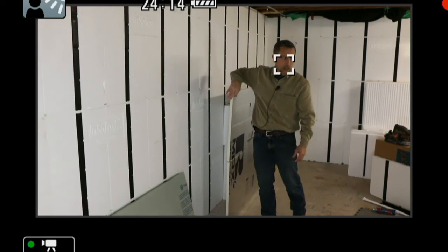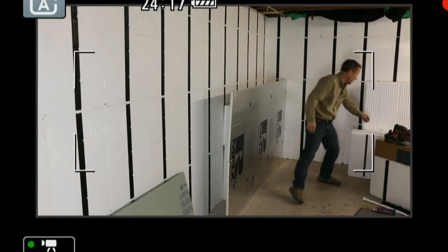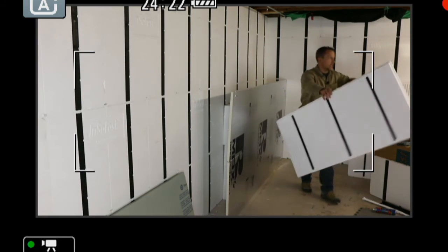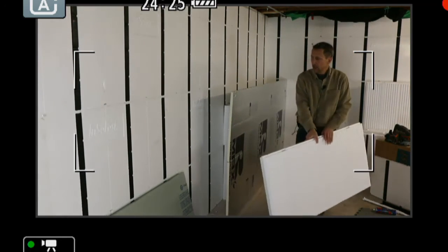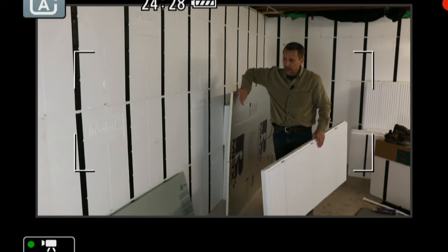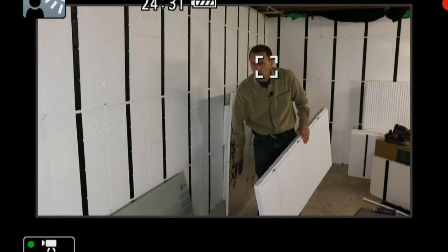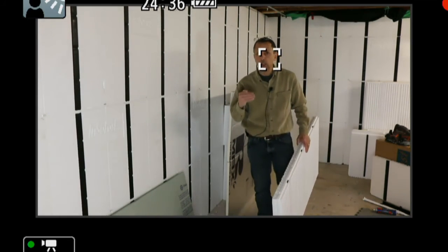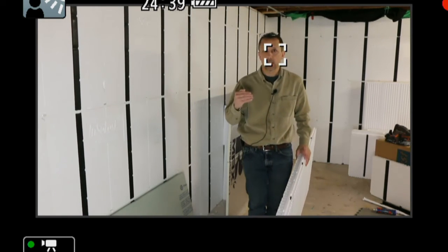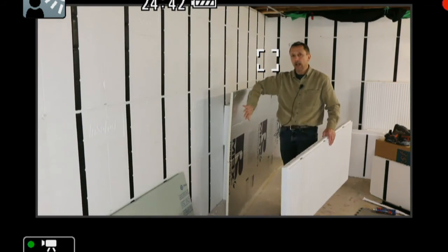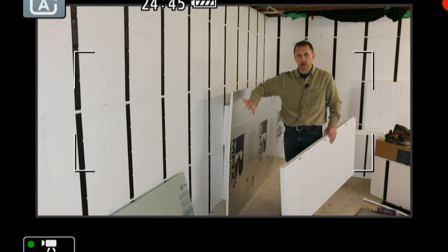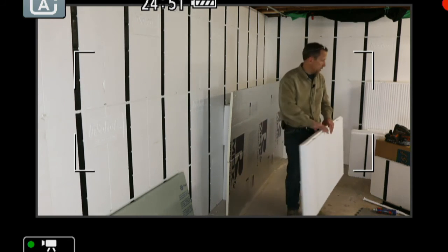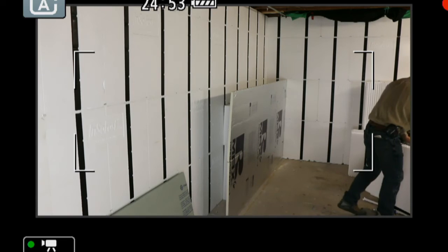This 1 inch would work really well on our InSoFast EX, which is an R10.5, so that would give you an R17.5. This is only going to give you an R14.5 if the building code official's really going to be a tight stickler on that. What you'll need to do is get 1.5 inches of pink board, which is an R7.5, and an R8.5 will give you an R15. But just as simple as it can be, you're going to get